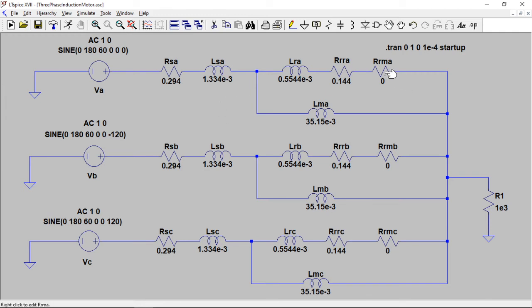So with a locked rotor, or basically a rotor that's just starting up, you've got a lot of current flowing. When you're at a slip of 0.2, 0.3, or 0.4, it's going to be much smaller. For a slip of 0.02, we saw about 18 amps roughly, while for a starting rotor, a locked rotor, it's around 150 or so. Okay, so that's pretty cool.